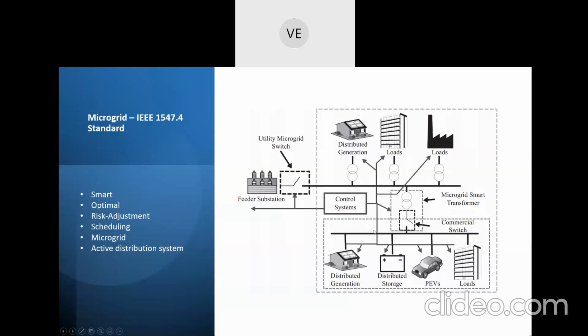So if you are too much taking care of the values, then you can even design the objective based on voltage deviation minimization. That means actual voltage minus the reference voltage, or vice versa. So this could be minimized. That can be another objective. Or some other operator can give preference for power loss in the system. So it can be power loss minimization also sometimes.